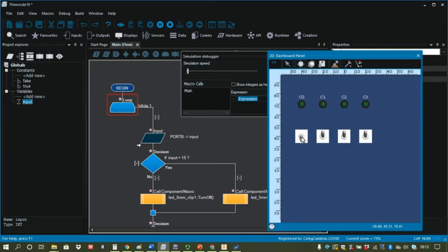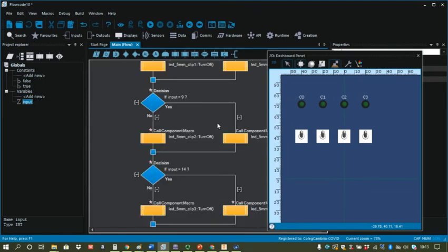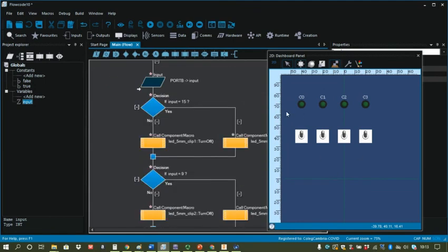So obviously doing it with a microprocessor has several advantages. It's obviously going to be much quicker to write this program and just connect LEDs to the correct output ports and switches to the correct input ports. Obviously we'd need resistors and possibly transistors for buffering on that as well.